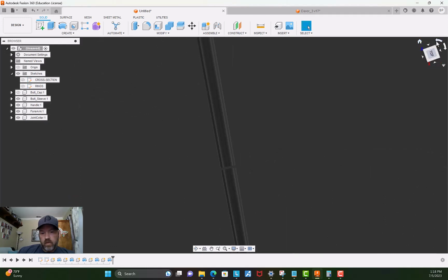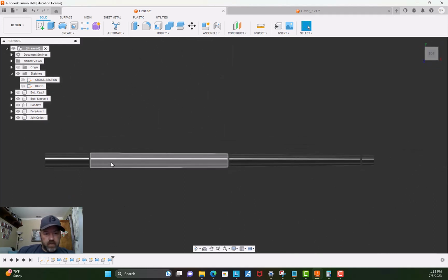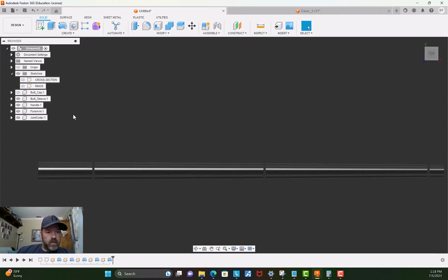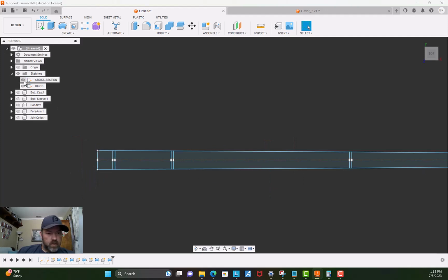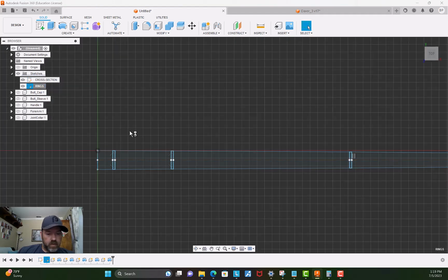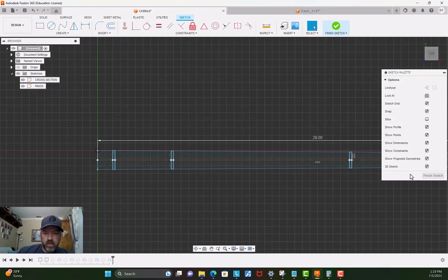top view, we can see we kind of have a cube, but we're missing these ring sections. Okay, so let's go ahead and fix that. So I'd like to turn off all of these guys and hit rings. And from here, I was missing this center line, so I'm going to actually hit this center line, Control C. I'm going to edit this sketch of rings, Control V. So now my center line is pasted in.